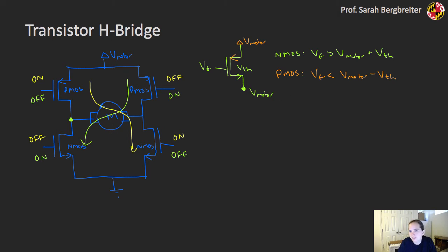Now, one other thing that I didn't include here initially is the idea of including flyback diodes across these things. And I didn't sketch those originally because, at least for MOSFET transistors, those are oftentimes built into the transistor. I often have a diode path between the source and drain like this, and so that effectively gets me my diode automatically in my H-bridge circuit.